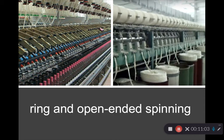It takes carded yarns to do it, but it produces heavier yarns like your denim and your poplin and maybe something that went into towels. It's not a great process for manufactured fibers, but it's usually staple fibers that are produced very quickly in open-ended spinning. Ring spinning is more common for your combed fibers, so your finer yarns that are meant to be made stronger.